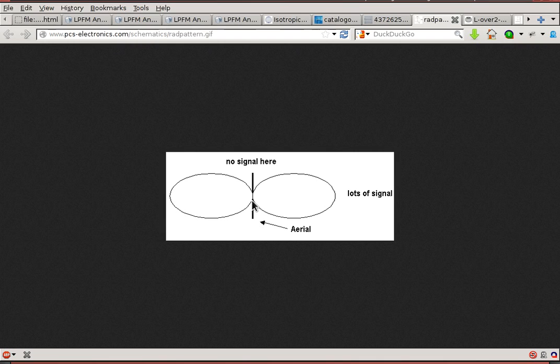What this means is that since the signal isn't going towards the ground with the same signal strength, like perhaps if this was a sphere, it might be going down to here. That signal going to the ground is what pushes out your prohibited zone towards the ground. So by using a dipole antenna and other antennas, we'll get to it in a minute, it essentially flattens your signal area so that it doesn't send so much energy to the ground. That means that the prohibited zone, the interference zone, doesn't get as close to the ground.